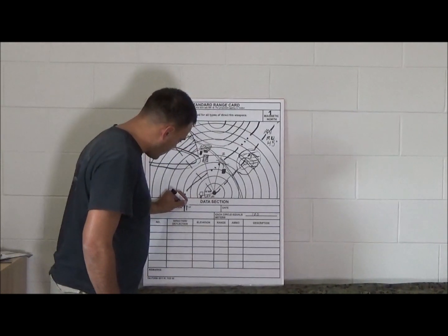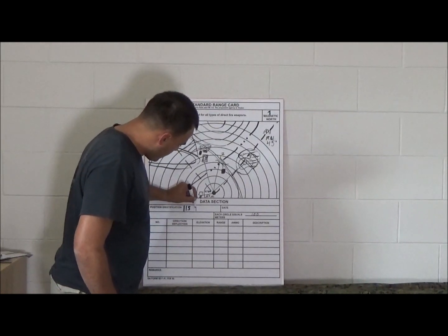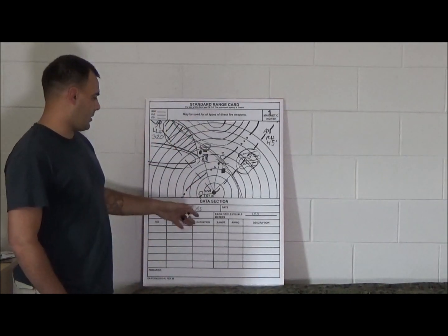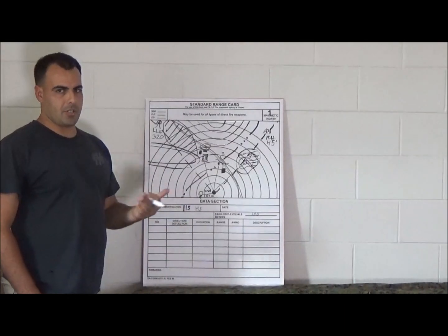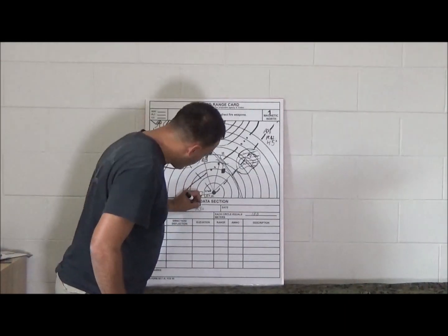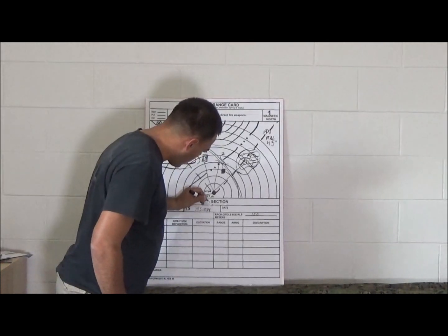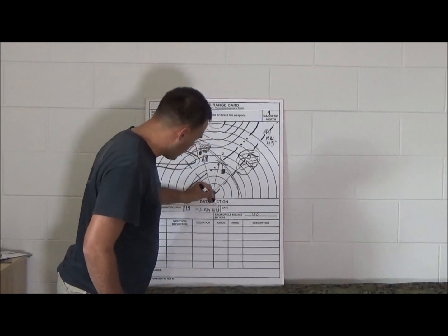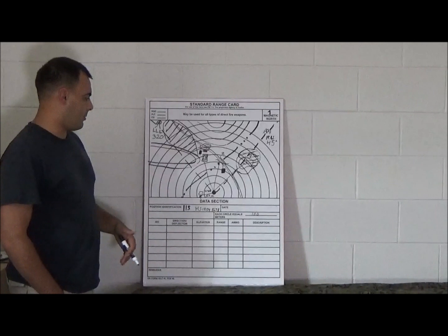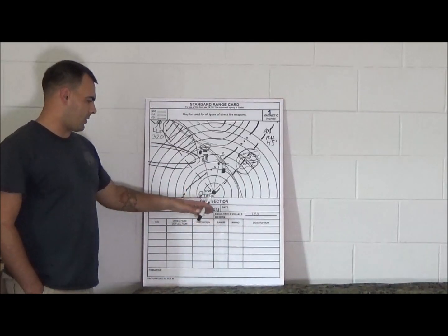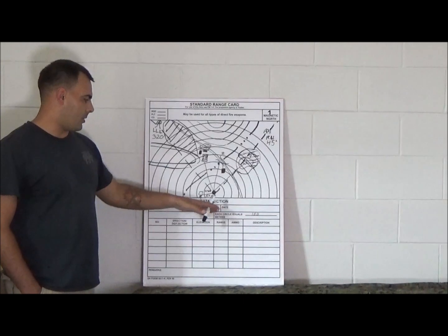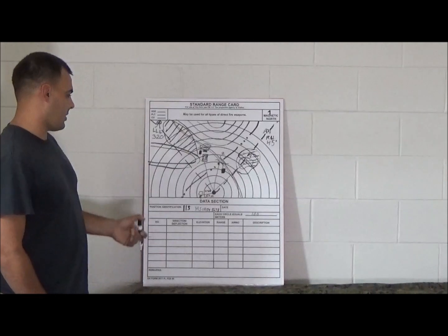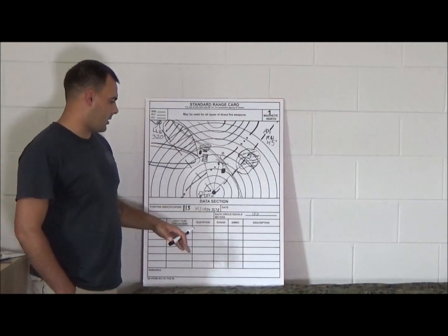So we'll use grid zone designator, 2-letter code, the 100,000 meter square identifier. If you watch my video, Introduction to Land Nav, you'll know what that is. And then the grid. An 8-digit grid will get you within 10 meters of the position. A 10-digit grid would get you within 1 meter, and a 6-digit grid would get you within 100 meters. So an 8-digit grid is about the biggest I want to go.